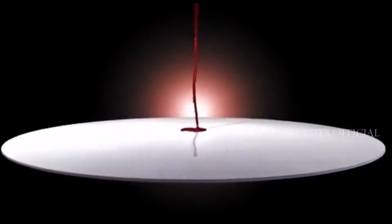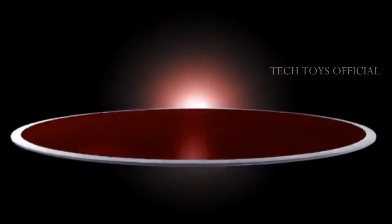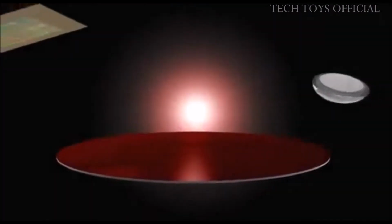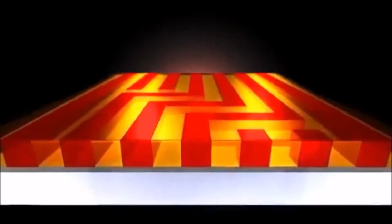The silicon disc is spin-coated with a photosensitive resist. UV light transfers the circuit structures depicted on a mask to the wafer. The exposed parts of the resist are soluble and are removed by a developer.